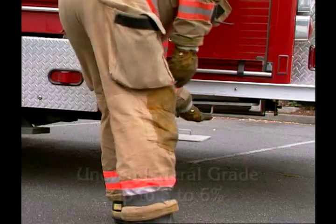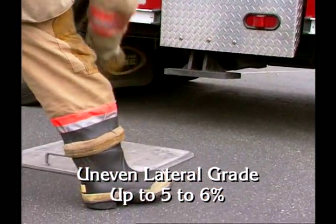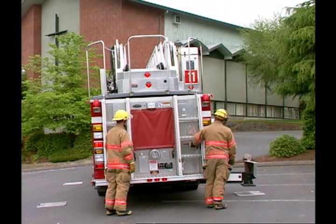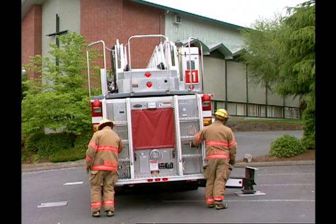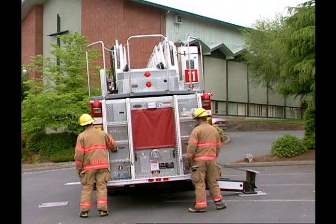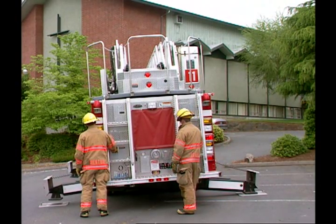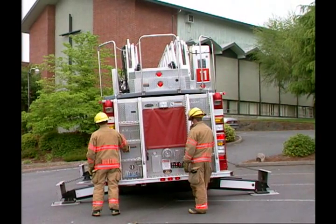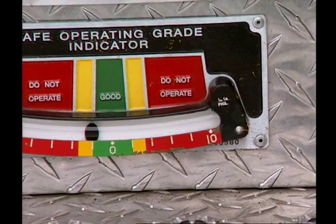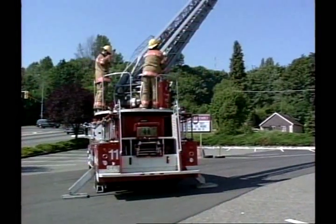You can stabilize the truck on an uneven lateral grade of up to 5 or 6%. Most manufacturers of aerial devices recommend that you lower the stabilizers on the high side of the vehicle first. Lower them only to the point that they contact the ground. Then lower the stabilizers on the low side of the truck until they raise the low side to be even with the high side. After the apparatus is stabilized, it is best to operate the aerial device over the high side of the truck.